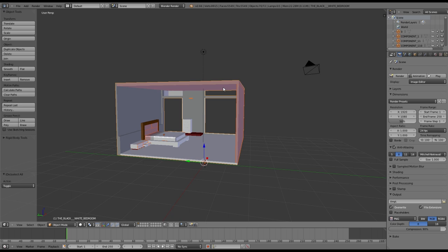As you can see, it's gone a yellow color as opposed to this orange color. You want to make sure one of the objects inside the scene you've selected has that yellow outlining, and that's just by holding shift and right click. So it'll make sure the program knows, okay, this object here can be used as the parent. So we're just going to go Control J to join on our keyboard, and as you can see, everything's now gone yellow.